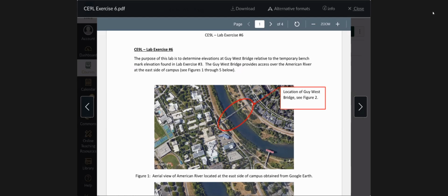I guess you define this more as a topographic leveling exercise, where we're backsighting a known elevation like we have to do in any leveling exercise, because you need a known point to start with, and we're calculating the height of the instrument, but all subsequent measurements after that are all foresights. Okay, so keep that in mind today.